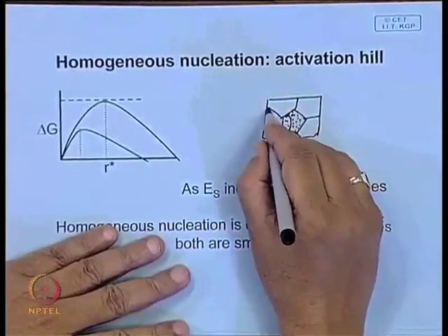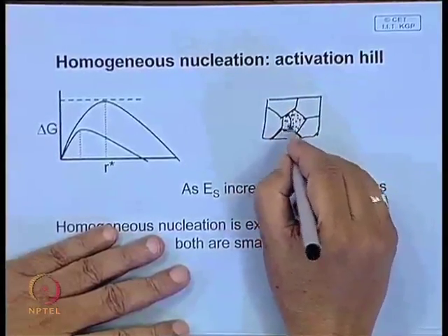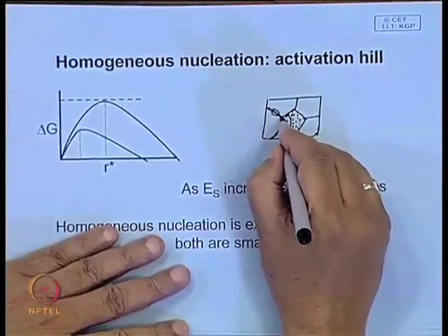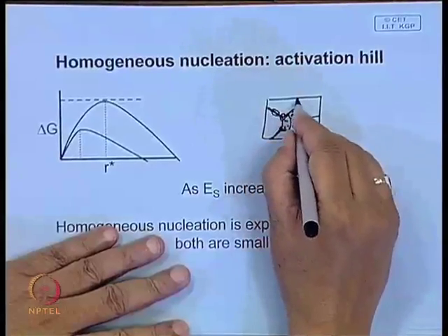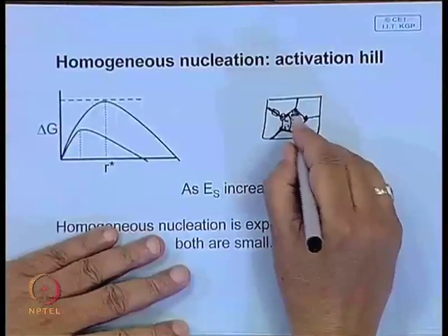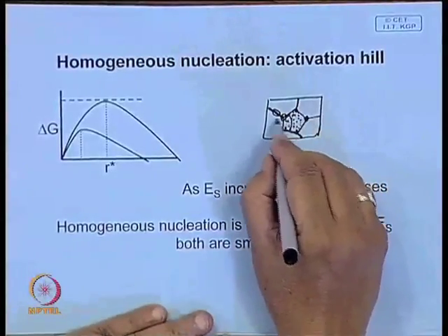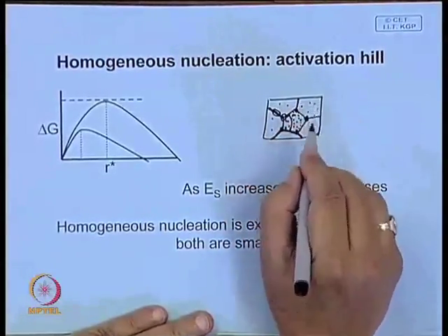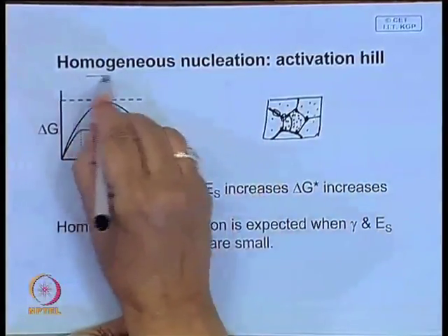You have to suppress it, because the grain boundary provides a favorable nucleation site. So normally precipitate will like to form here, primarily at the grain corners and the grain faces. Now, to get good precipitation strengthening, you have to have a nice array of precipitates within the grain, and this can be promoted by promoting homogeneous nucleation.